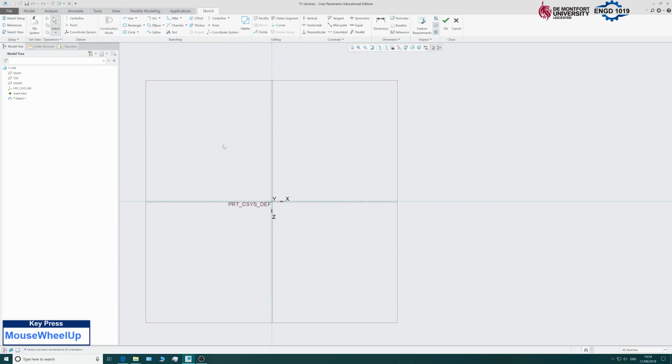The first thing I'm going to do is the overall outline for the shape, and it's basically based off a rectangle. So I'll click the rectangle tool here, and you'll see that the cursor has now changed to this sort of X symbol. If you drag the cursor towards these lines, it automatically snaps to them, which is useful for drawing our rectangle.